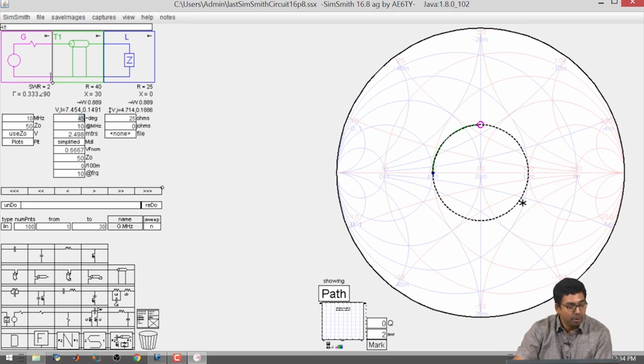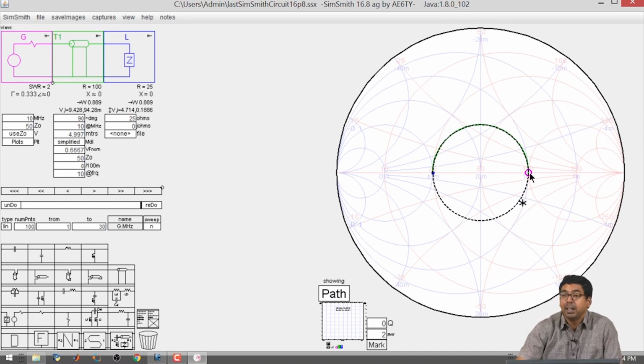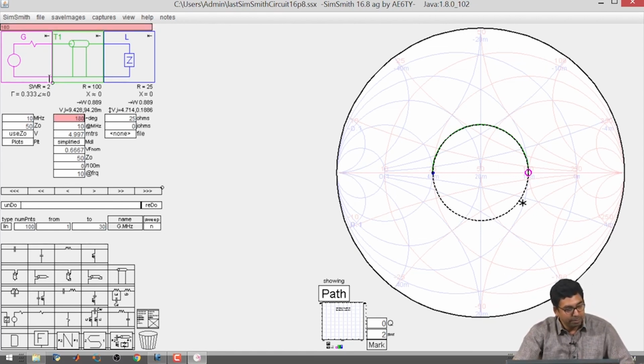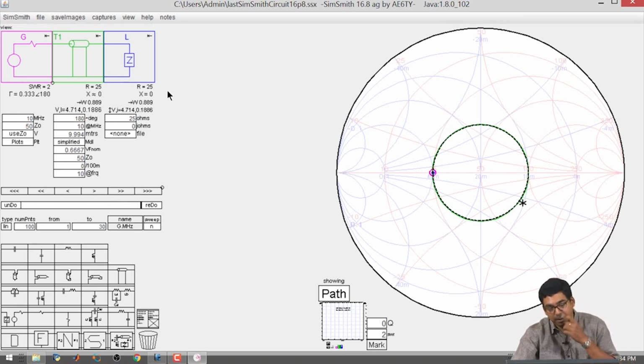So, if I go for 90 degrees to be the phase provided by the transmission line, I will reach the diametrically opposite point in reflection coefficient, a 180 degree change. So, the entire Smith chart can be traversed with a 180 degree phase shift of your transmission line. It will form an entire full circle. So, this is one thing that we have to register in the mind.